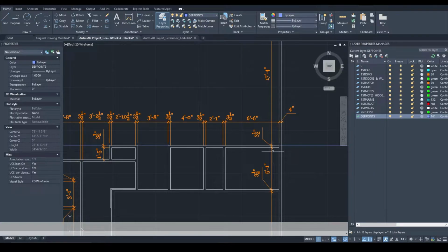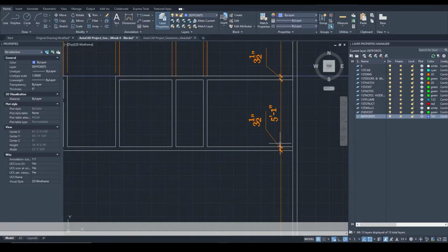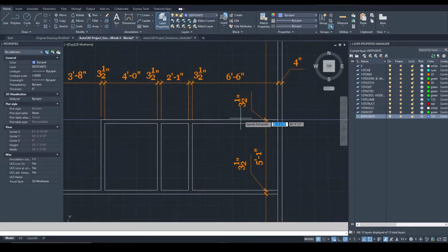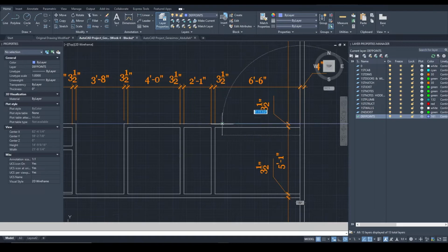And the way you draw interior walls in this case is without sheeting. So we're literally going to be drawing the stud walls, which are 3.5 inches. As you can see, 3.5 inches, 3.5 inches, and so on. In this case, you can and you should use regular lines, not polylines, and type in L, space bar, and start from this point and go all the way up to 6.6.